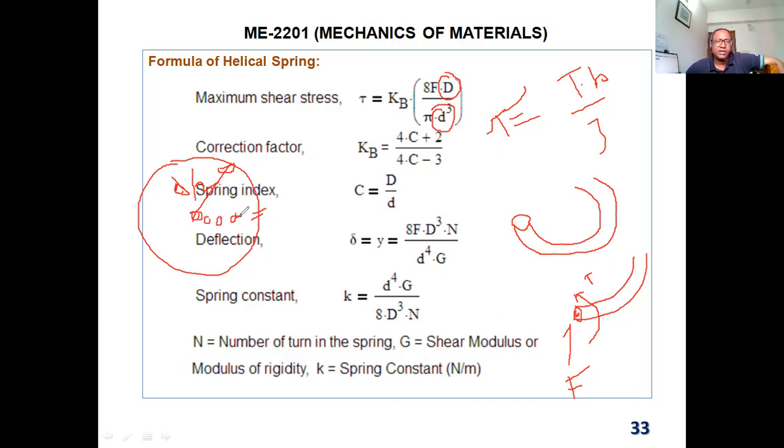Now, if you design a part, and you take this radius instead of the outer radius, then what will happen? You get some value. Say your shear stress, you are getting 800 KSI, kilopound per square inch, right?